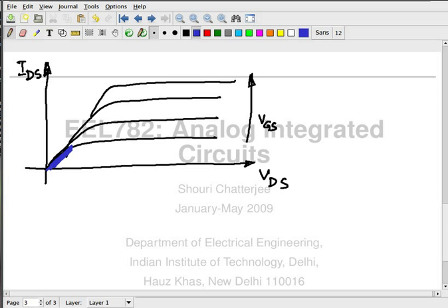So at a particular gate voltage, the density of charge in the channel remains constant. So when we increase the drain to source voltage, since the number of carriers is constant, a particular amount of current, depending on the carrier density, will flow, not more than that. So the current saturates in that condition. Given the fact that there are only so many electrons, n number of electrons in the channel, there is only so much current that can flow, not more than that.